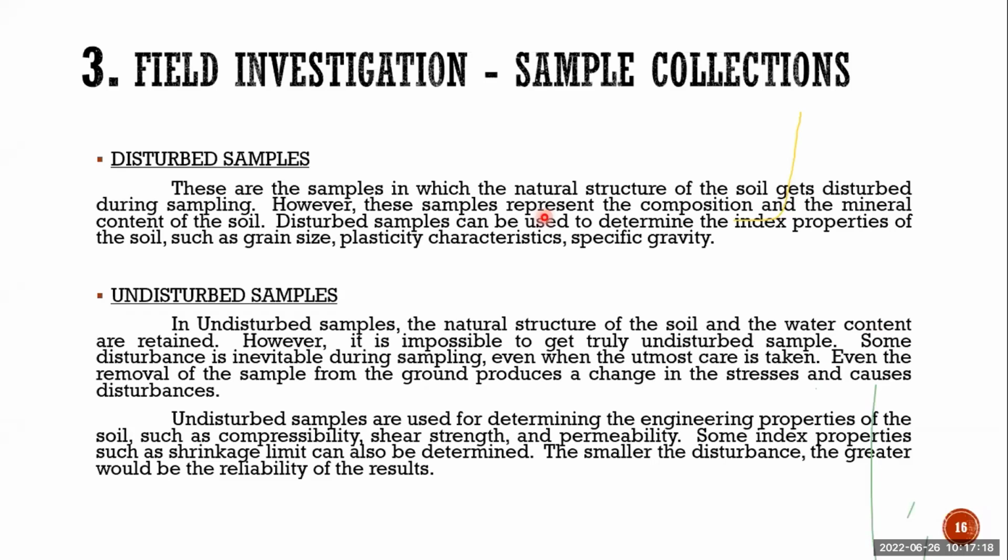Immediately after the sample collection, if we keep the sample in the sample bag, then we can preserve the water content in the disturbed samples. In the disturbed sample, we can perform tests like grain size distribution, plasticity characteristics, and specific gravity. And in the undisturbed samples, we can know the compressibility characteristics of the soil.